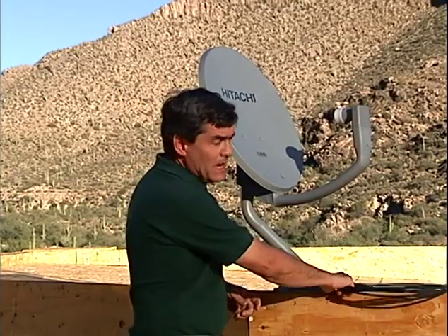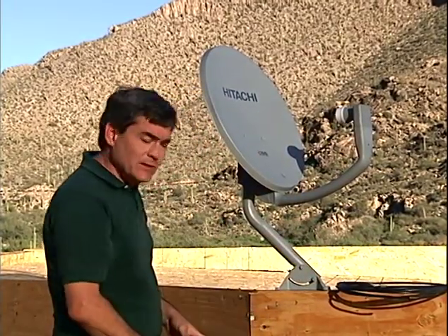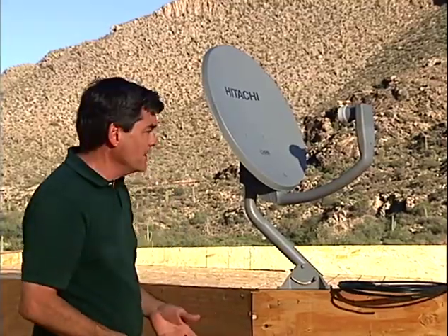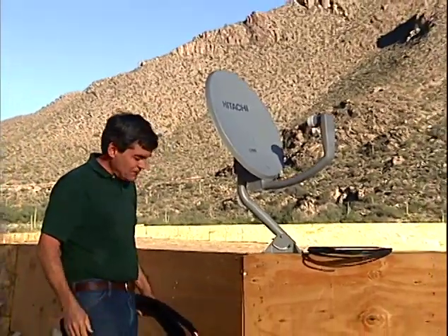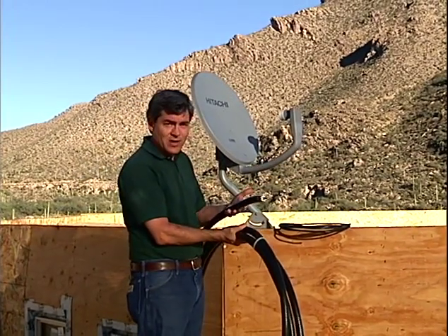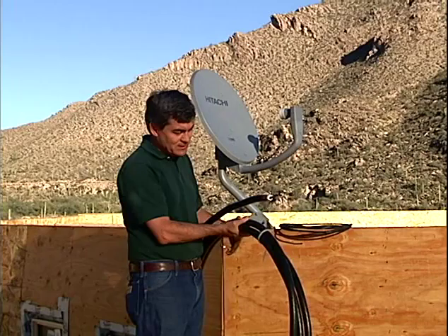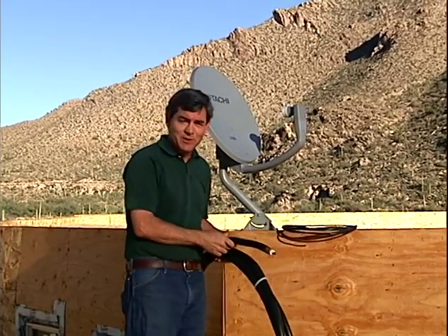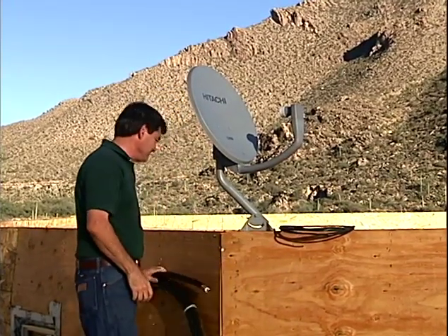Now, you could, however, take the 12.2 GHz signal and feed it right down to the receiver and do the block conversion there. But in order to do that, you'd have to use something like this microwave hardline at $10 a foot to do the job. Really cool cable, and this produces a really nice installation, but we don't recommend it.